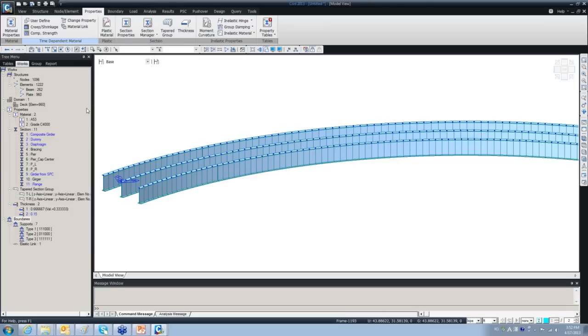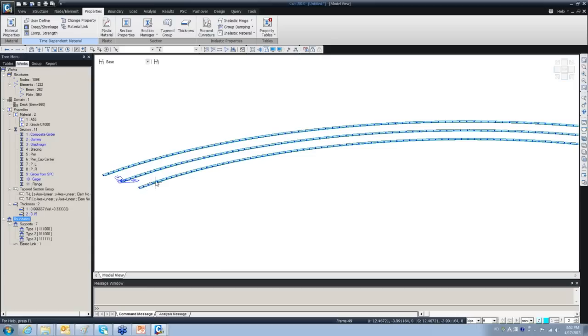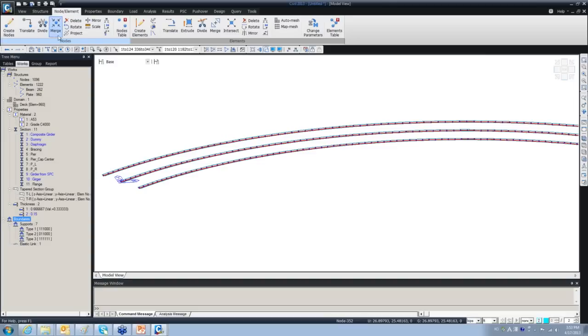Okay, and now what happens? I want to just switch the entire girders. Let me select all, and then apply only the flange. So what I'm going to do, having the flange model as a beam, the web model as a plate, and then the bottom flange also created as a beam. Again, I'm selecting them all, and going to the node and element and extrude again.